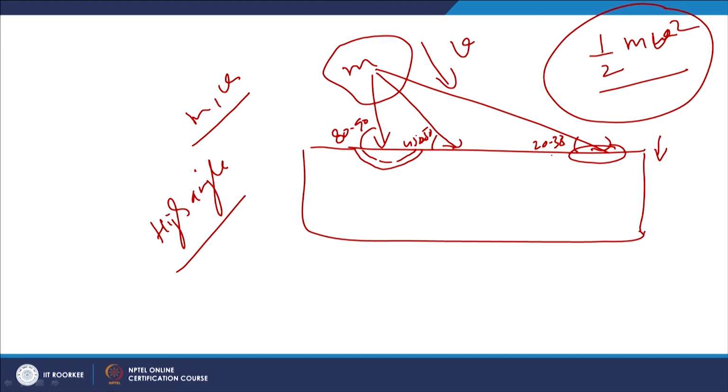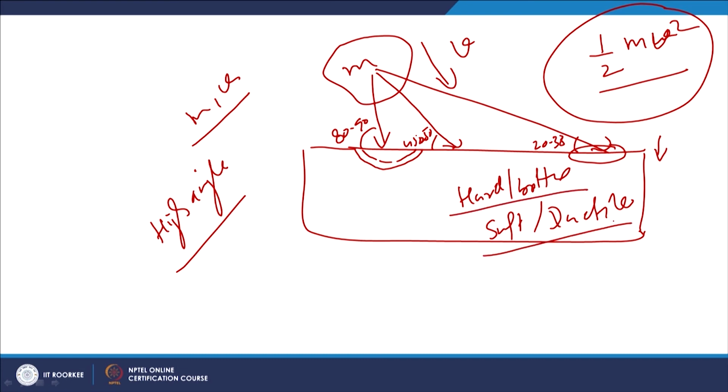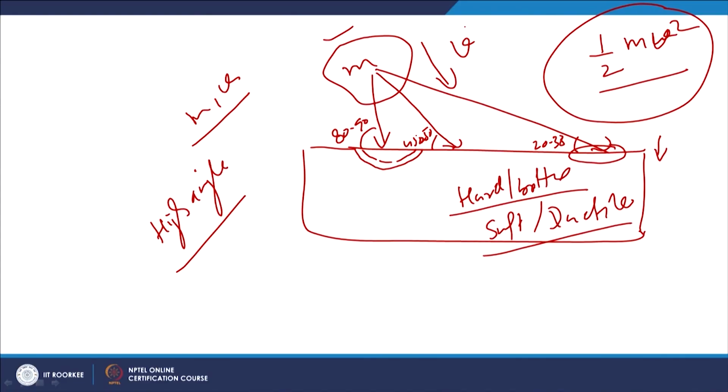However, depending upon the type of metal, whether it is hard and brittle or soft and ductile, the extent of erosion which takes place can vary significantly. So, it is the type of material of the workpiece that will significantly determine the loss of material from the functional surfaces when impingement at different angles takes place, even with a particle of a given mass and a given velocity.